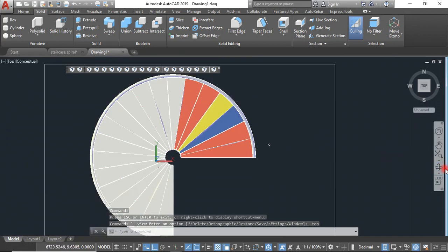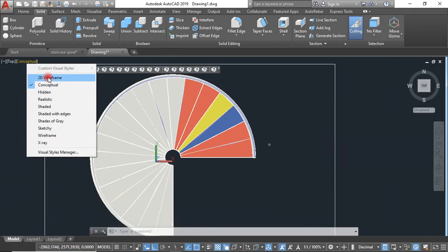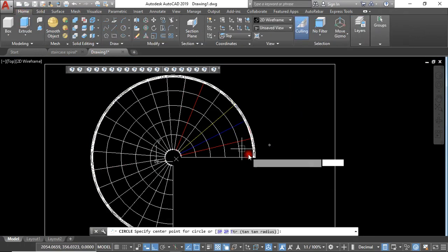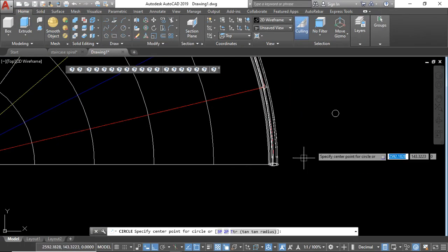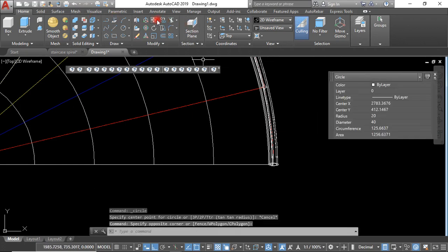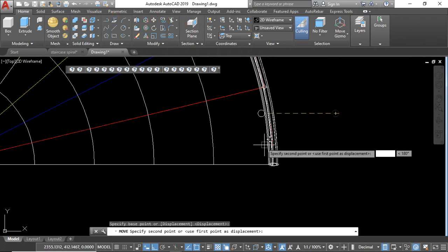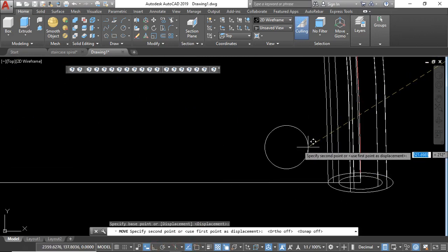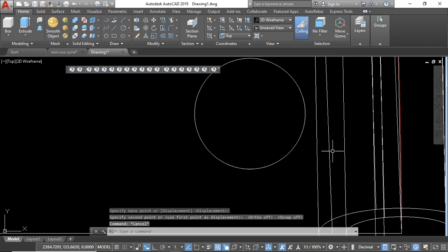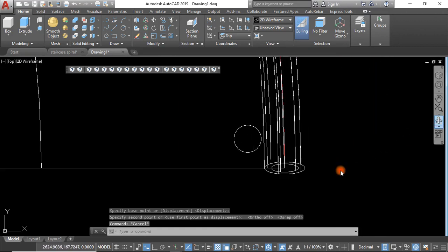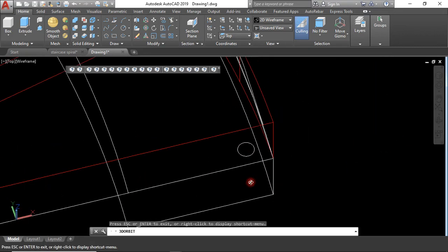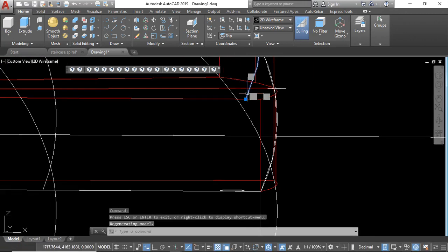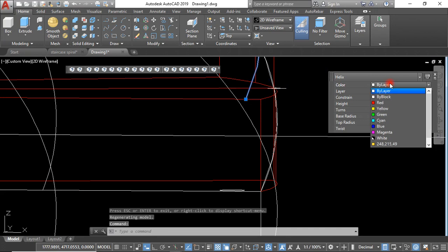What else is remaining is the post that you hold the handrails together. So you can just come here and go to top. Then maybe go to wireframe. Let's do maybe a simple circle. You can even use this one here.